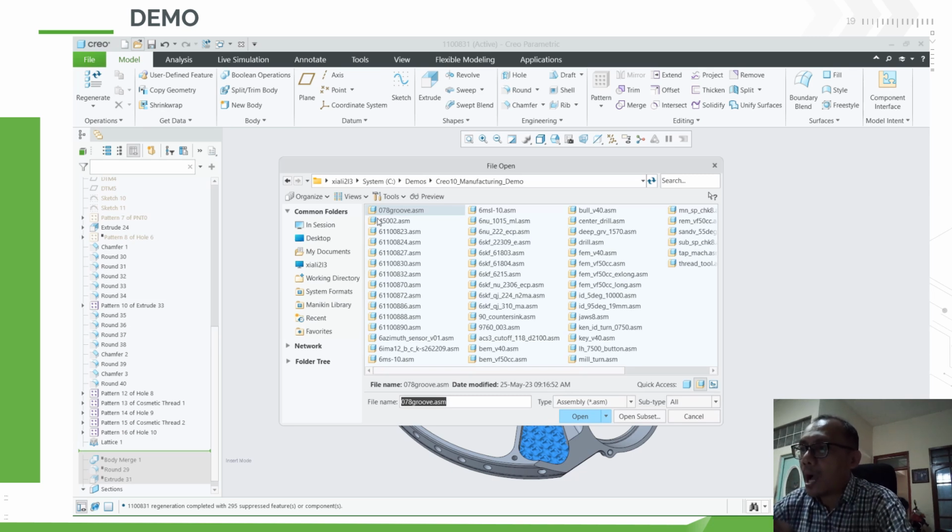The last thing I will mention is we have always had the ability to do density variation on some of the other lattice types. But as of Creo 10, we can do that now with formula driven. We can vary the density based on simulation results, in the new formula driven lattice within Creo 10. That is the additive side of what's new in Creo 10.